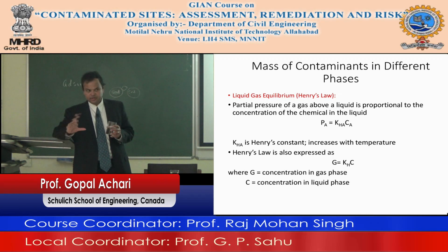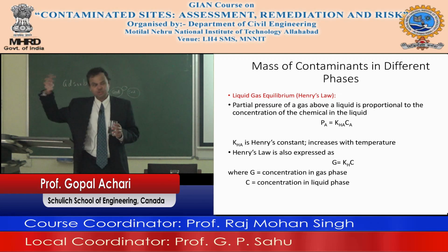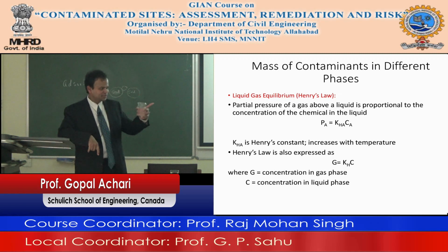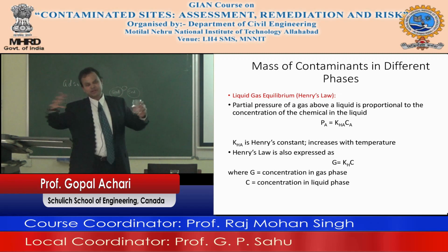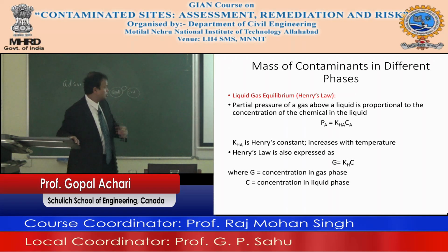Because think about it, in 15 days you got the soil vapor out, most of it you can get out in a very short period of time, but after that the tail effect lingers on for months. Take an example of that. How long is it going to take to replace that air as compared to all the benzene from the dissolved phase coming out?